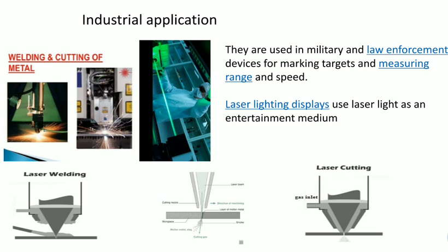Here, there are some advantages in laser welding. As compared to other welding, a strong joint will be obtained. There is no distortion of shapes here. The welding spot we can easily identify. Here no foreign material is used, so impurities cannot enter. Now this is very helpful for microelectronic devices, because these components are very heat sensitive materials. That's why laser welding can help with those components.